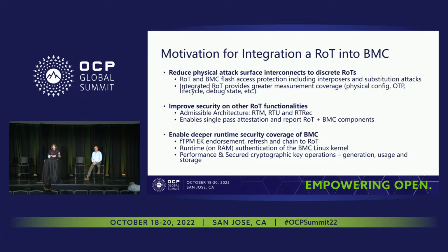Another motivation was externally with root of trust and taking measurements on flash chips. You get measurement, of course, of firmware, but configuration, like the device configuration, how it's set up with OTP fuses, what lifecycle state it is in, is debug enabled on the device. These are typically internal properties in the device that are equally as important as the measurement of firmware. So we want to be able to capture those and extend that coverage.